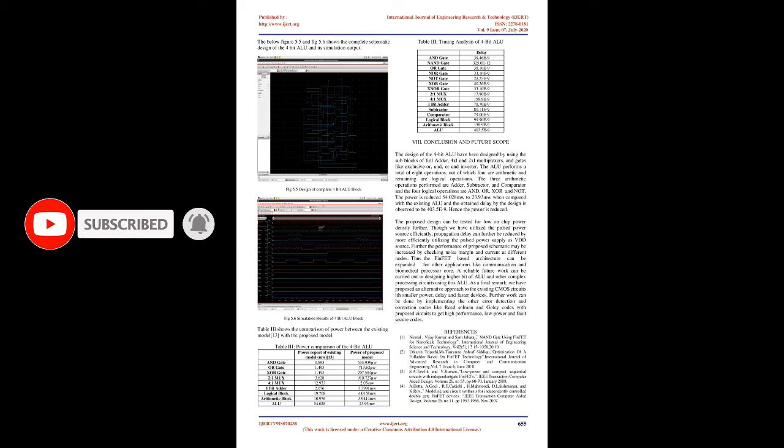In the above diagram, the full adder/subtractor has 3 inputs, so we take 3 inputs, namely A, B and Cin. Other than the adder/subtractor, all the operations only need 2 inputs. The functions are selected by a multiplexer with select line and then we obtain the output. 4.3 Design of 4-bit ALU. The 4-bit ALU is designed by cascading 4 1-bit ALU blocks. Each 1-bit ALU is composed of the following 3 components.